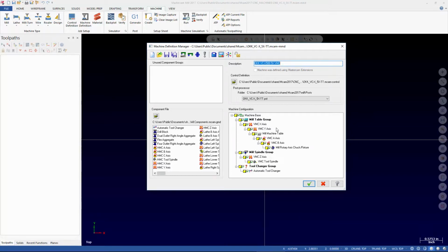For the layout of the machine configuration in the Mastercam machine definition, we could actually just use this as is. Oh, you've not yet got it going. Oh, that's okay. If you have any of the machine manuals, you can look in there, and typically the stroke diagram will give you the information of where that platter is.